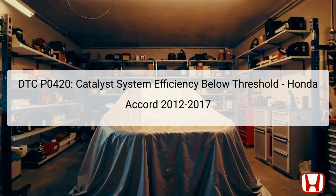It is located in the exhaust system, after the engine and before the muffler. The engine's powertrain control module, PCM, monitors the efficiency of the catalytic converter by comparing the readings of the upstream and downstream oxygen sensors. If the PCM determines that the catalyst is not working within specified parameters, it triggers the P0420 code. This diagnostic trouble code can often appear alongside other codes related to the vehicle's emission system, particularly if there are issues with sensors associated with the catalytic converter or misfires in the engine.